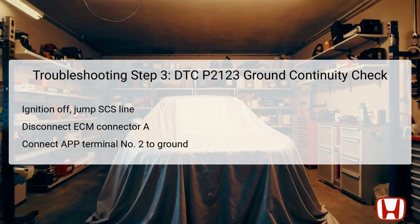This step is crucial, as it allows the technician to check for continuity and proper grounding from the ECM's connector terminal A35. Grounding is essential for circuit completion and functionality, and verifying it will clarify whether the issue lies within the APP sensor or ECM circuits. Proper attention to this step ensures that subsequent diagnostic directions are rooted in accurate assessments.